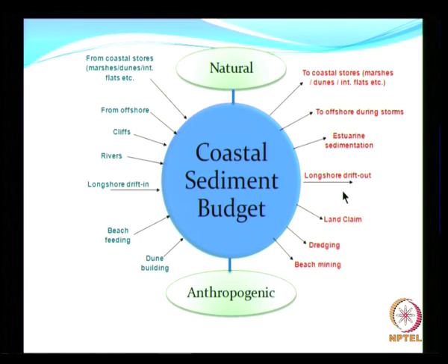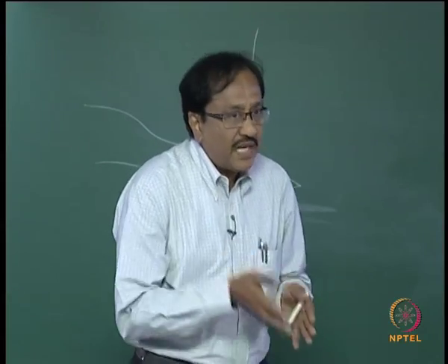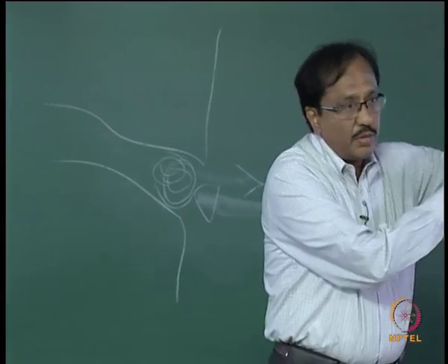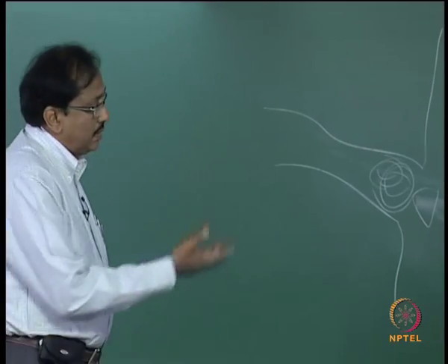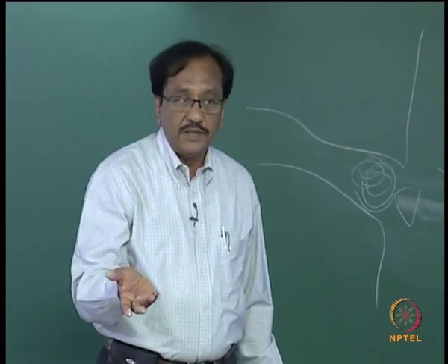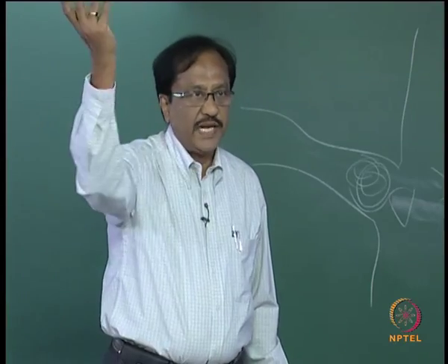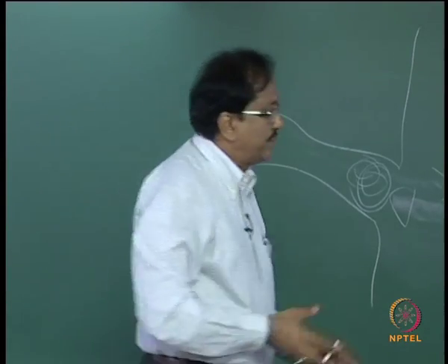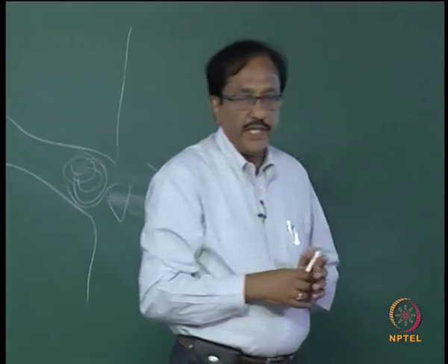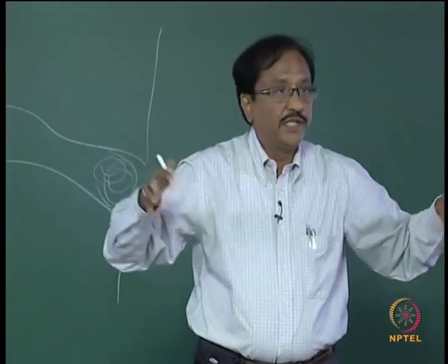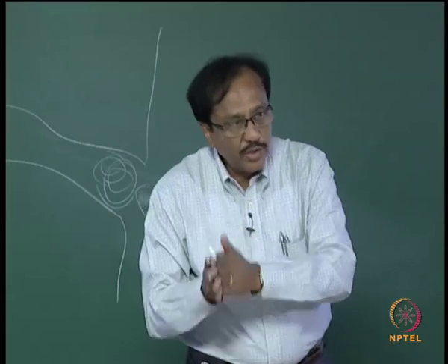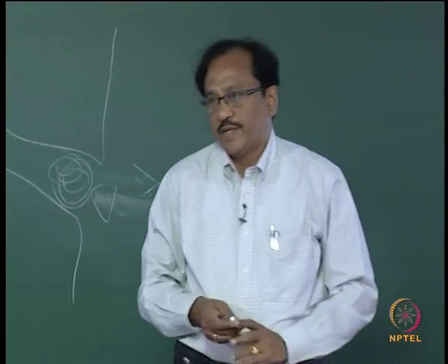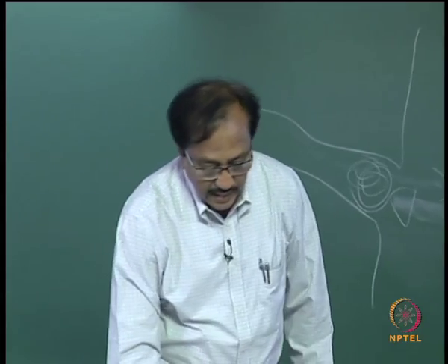Then again, littoral drift out: although you have some sand coming in, not all the sand is going to remain in one location; it can go away. Or land claim, then beach mining or dredging, these are all removals of sand from the location. So when you are talking about a sediment budget for a coast, you have to identify all these problems: how much sand can be expected to come into this area, how much sand is going to go from this area, etc. So, this needs proper planning.